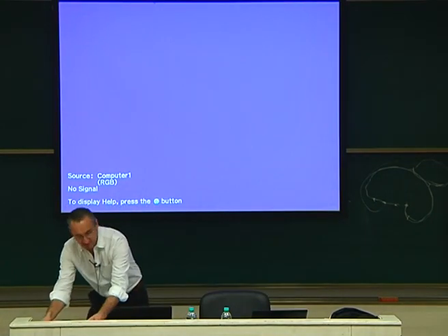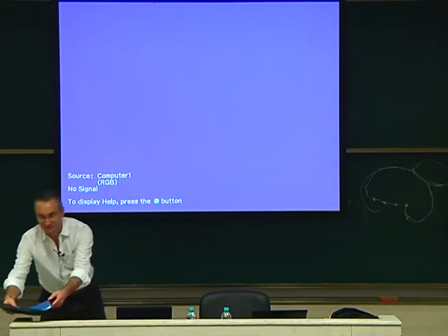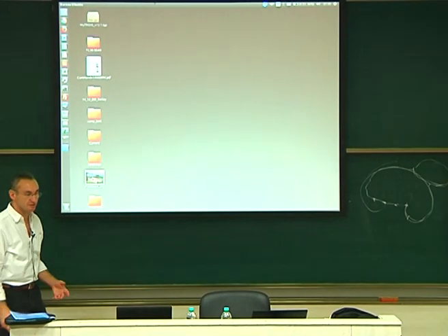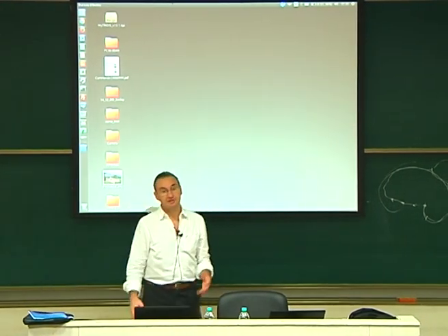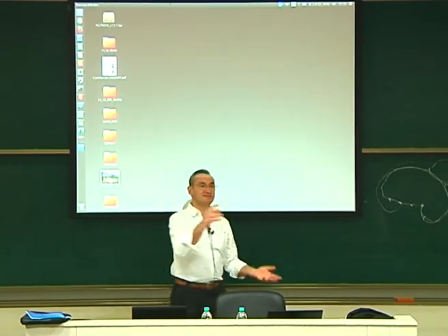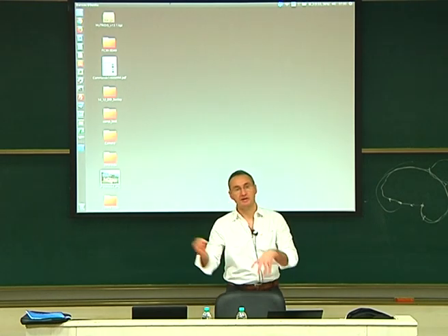Because some of you said that we need to know what it is, and in dislocation-based crystal plasticity, we need these parameters. We need to know what system is active when you pull in a given direction and so on.